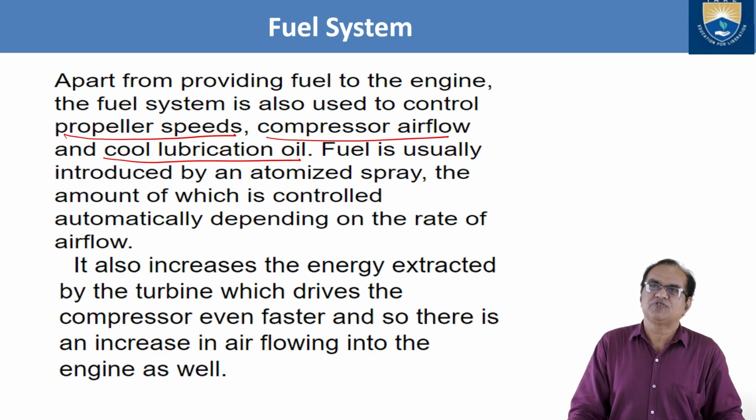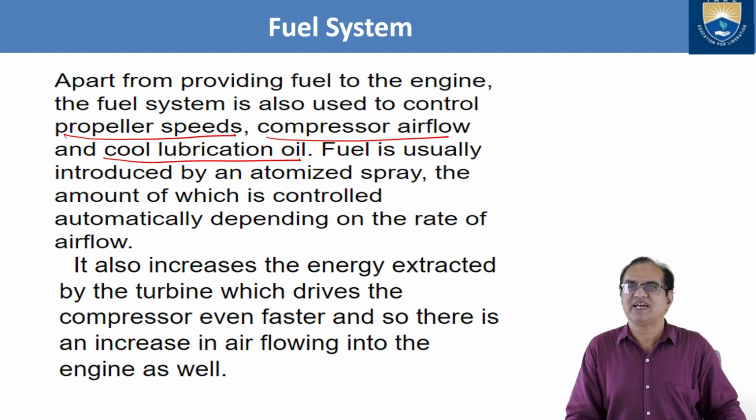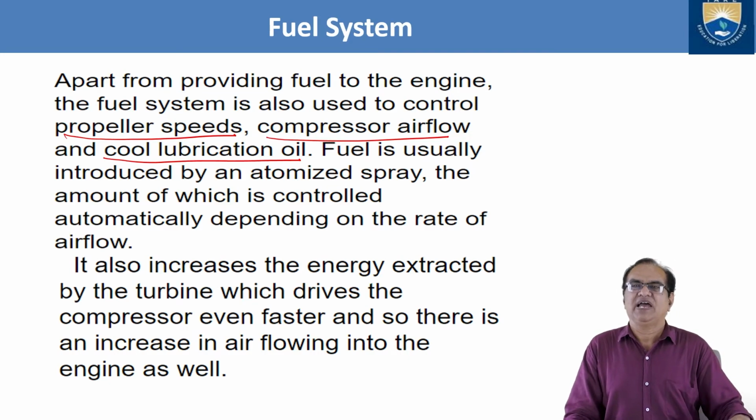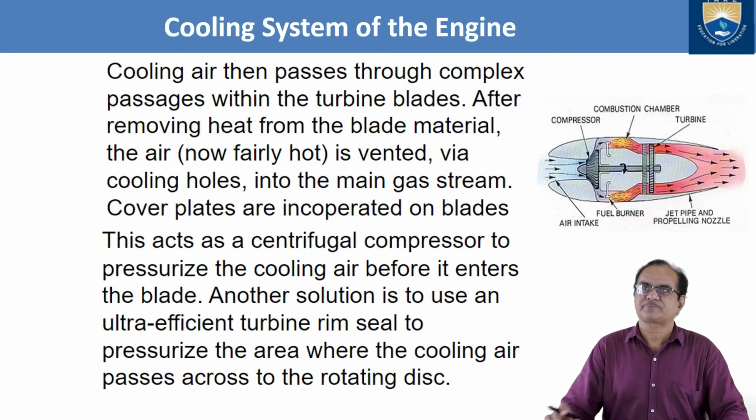Fuel is usually introduced by an atomized spray, the amount of which is controlled automatically depending on the rate of airflow. It also increases the energy extracted by the turbine, which drives the compressor even faster, and so there is an increase in air flowing into the engine as well.